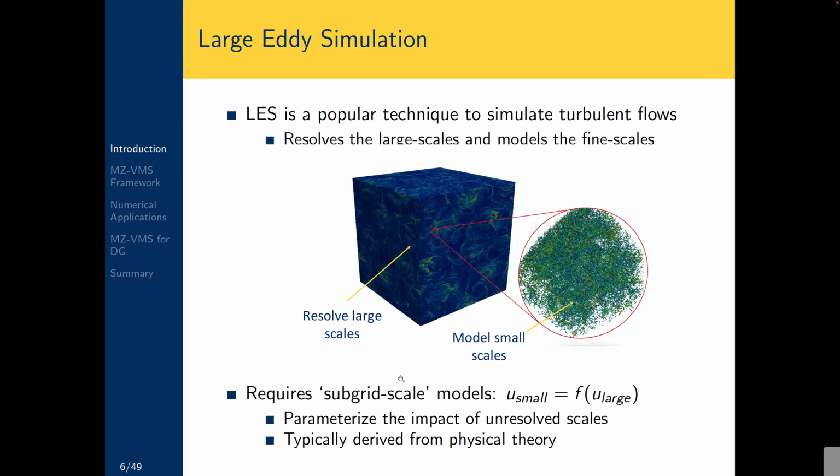All right, so when you talk about multiscale simulation and turbulence, what do we do for handling these problems? Again, in turbulence you have this wide range of length and time scales. There's also a lack of scale separation, so things constantly cascade from the large scales to the fine scales. And so you need to either resolve everything or develop good models.